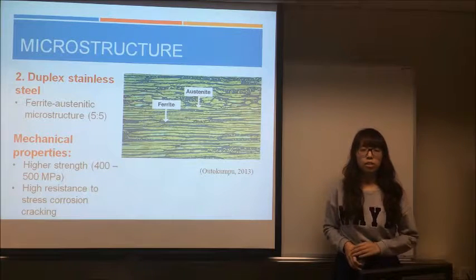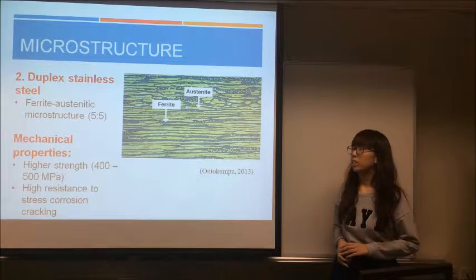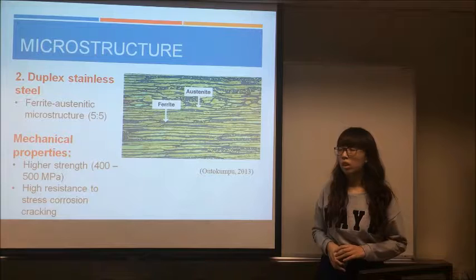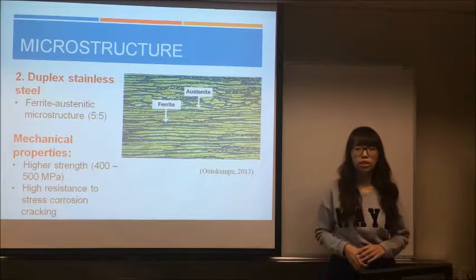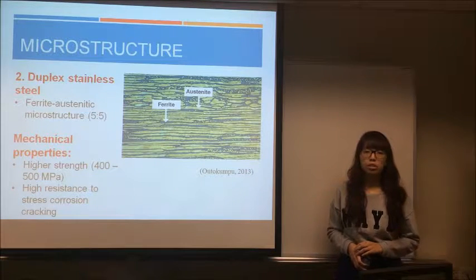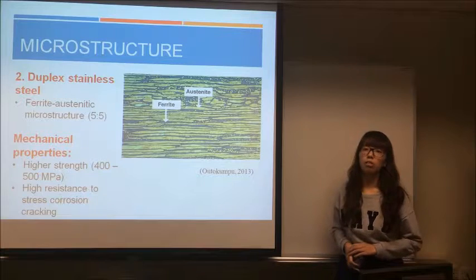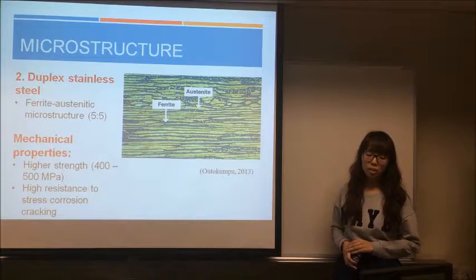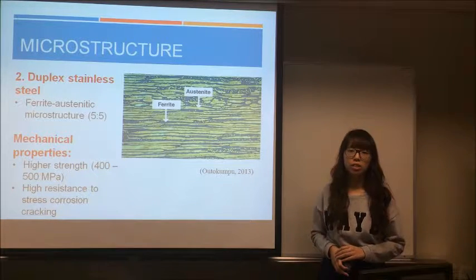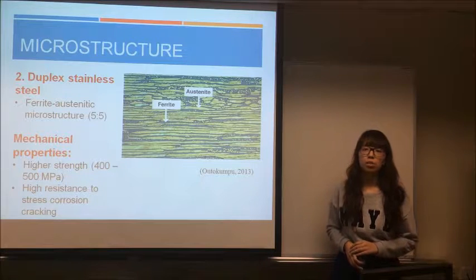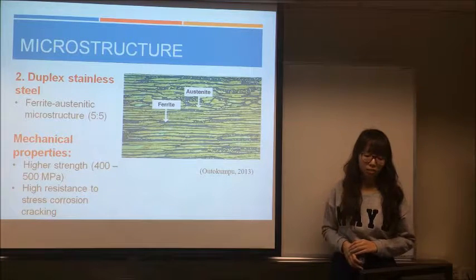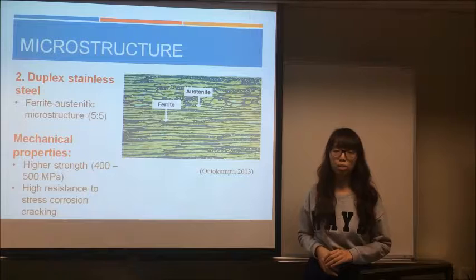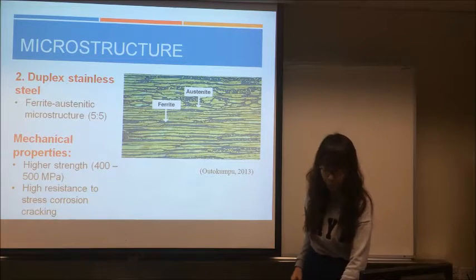The duplex stainless steel has a high strength, about 400 to 500 MPa, because of the finer grains of ferrite, and this can reduce the section thickness and therefore reduce the weight. Also, it has a high resistance to stress corrosion cracking.